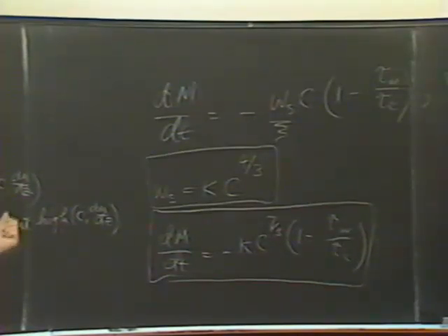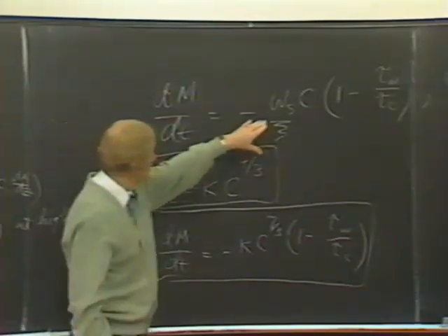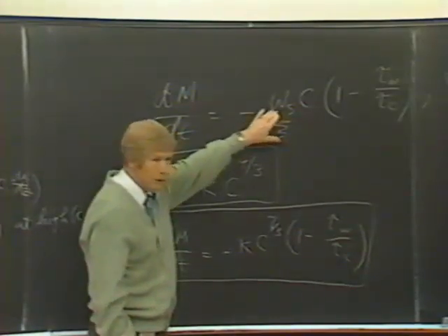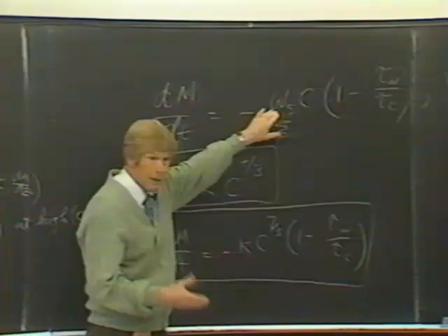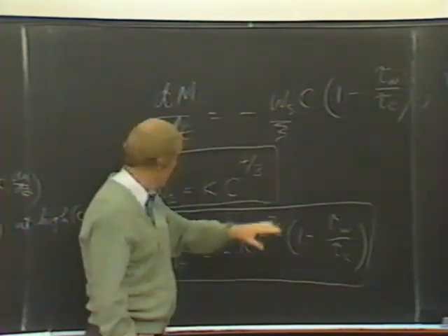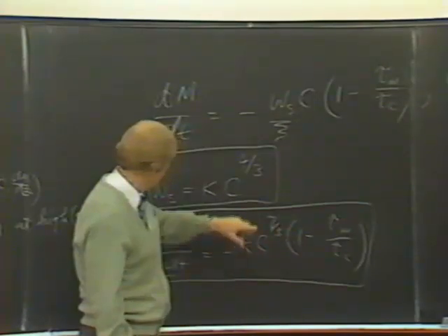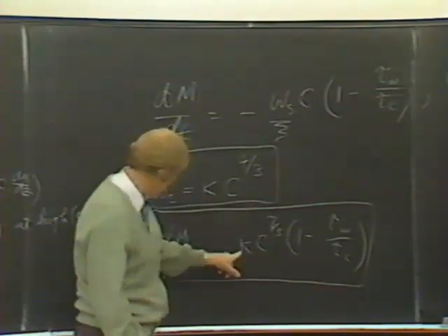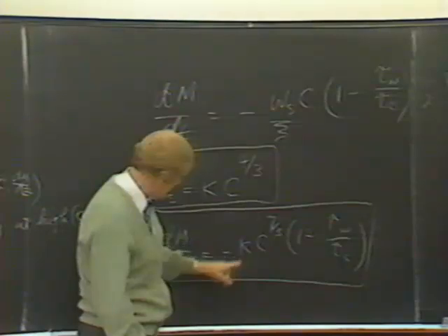This is Camp's G. You calculate the power dissipation rate for the whole flow divided by the viscosity to the 1/2 power, and you'll see that comes out with a dimension of per second.